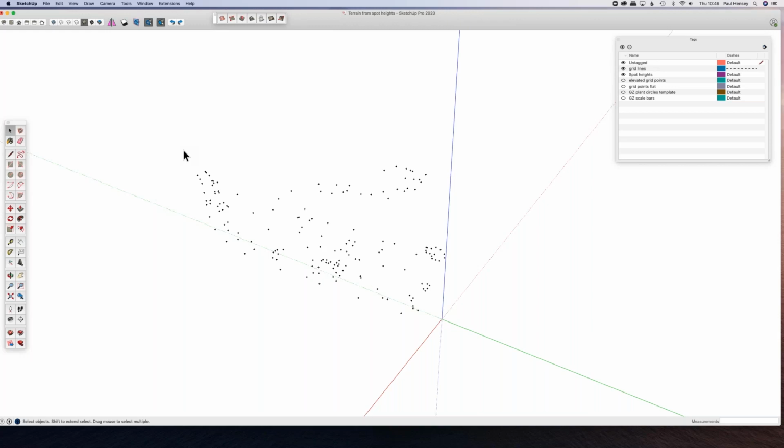When you generate contours, it takes that same data set and works out the approximate link to all of the points that are at the same level. And where two points aren't at the same level, it will interpolate between them and create a contour. So contours are approximations between data points, and data points are absolute.